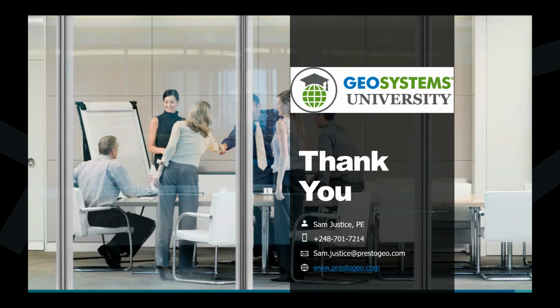Let's see here. I will do another question here. Do you have an approximate maximum slope for the GEOWEB, and do different fills make a difference? So yeah, the maximum slope that the GEOWEB system can handle is around 55 degrees, so a little steeper than a 1-to-1. When you start getting steeper than that, you're going to lose material no matter how well it's confined in the GEOWEB system. It's really getting too steep for that. So about 55 degrees is going to be your max.